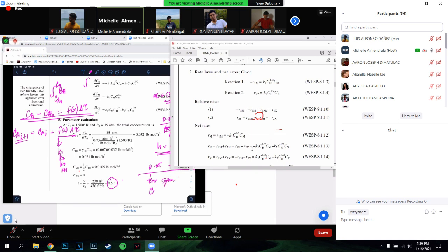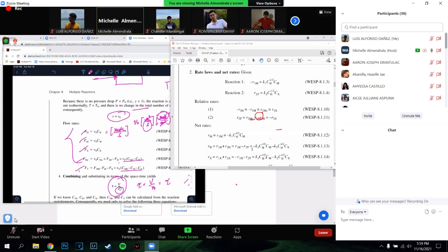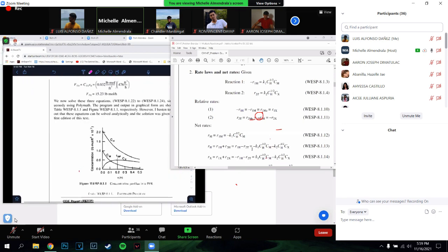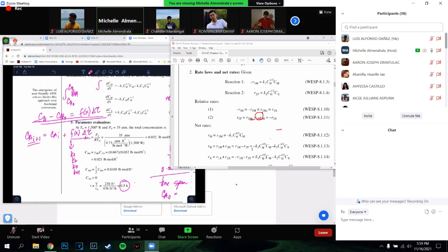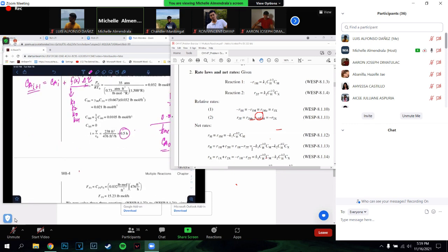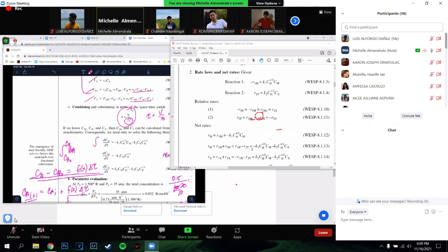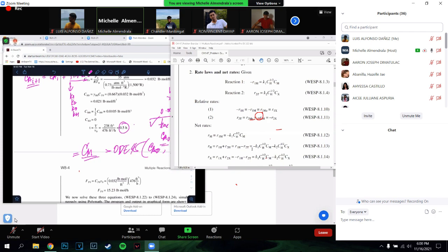And this is your CA0 initial, which is calculated here. What is that CA0? That's our CA. All the initial concentrations are calculated. And then plug these values of initial CA, check; given time span, check; ODE45, okay, time span, given, CA0, time span. And then what is our output? CM only, the concentration. And that will be the content of your ODE45.